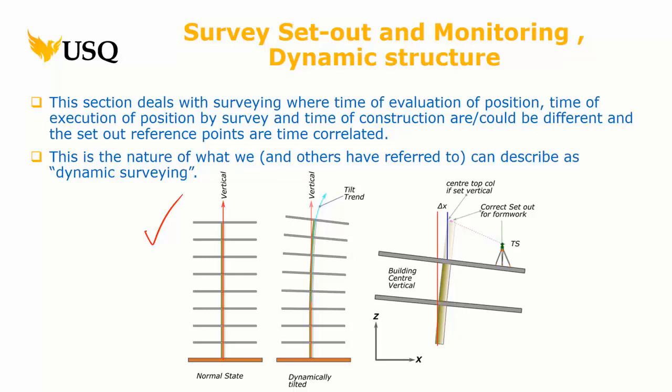So if you can ascertain that, and you put one on this side and one on that side, and it says it's inclined at 1.31 degrees and the other one's inclined at 1.77, you can calculate the vector using cosine directional vectors, which you'll remember completely from the metrology module. So looking at reality, there's the center column. We'll just use the center column for simplicity, and also because in the Burj Khalifa there was a center column system, a core column.